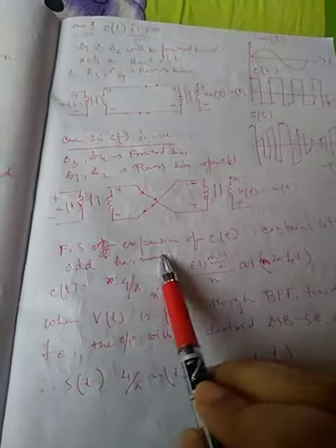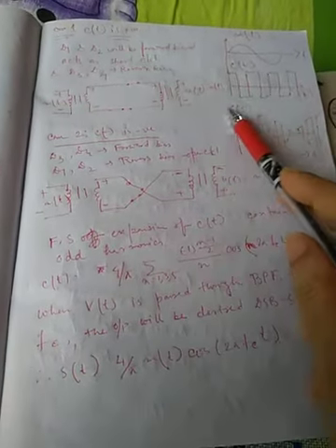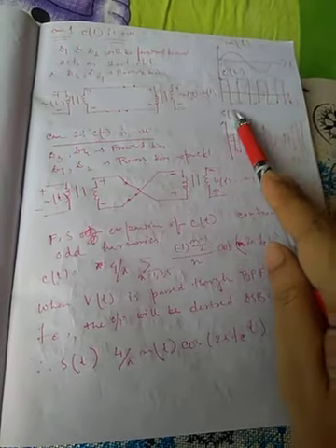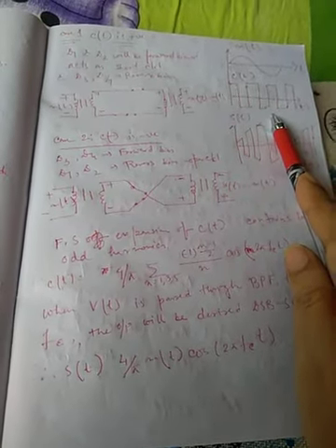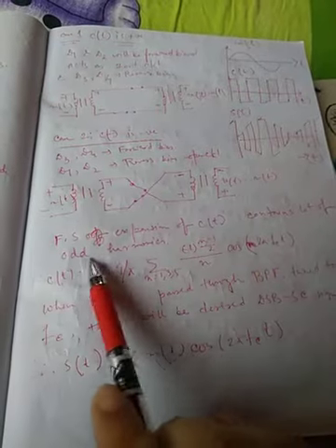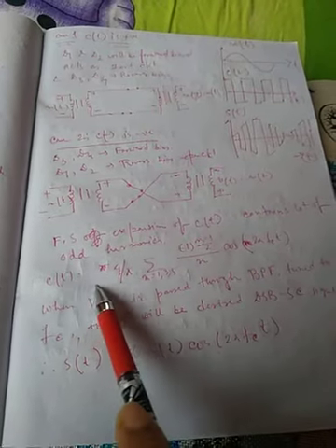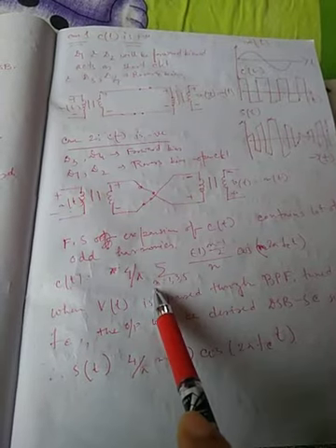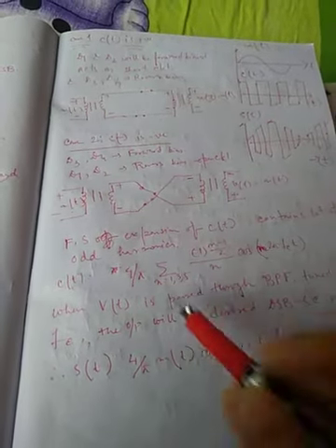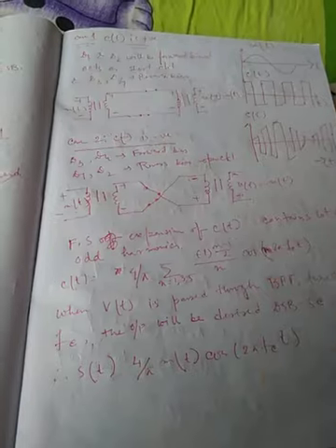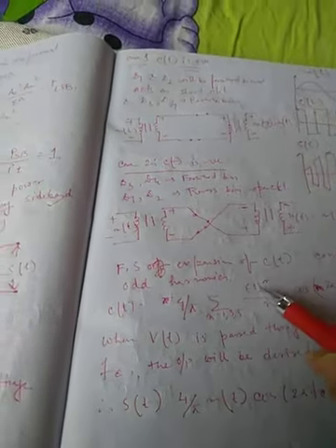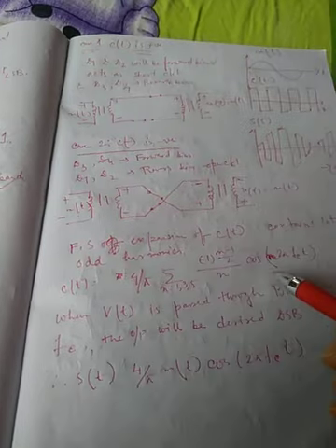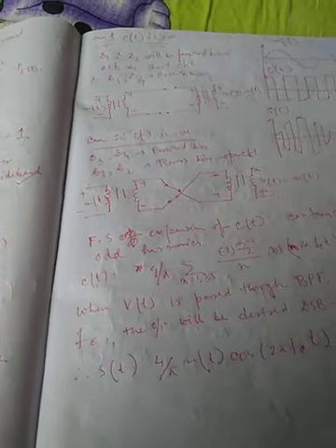Fourier series expansion of the carrier, this is a pulse train, right? So for the pulse train Fourier series expansion, we need to take, and that contains a lot of odd harmonics. So that is given as c(t) equals 4 by pi summation of n equals odd harmonics, that is n could be 1, 3, 5, 7, etc., (-1)^((n-1)/2) by n cos(n 2 pi fc t).